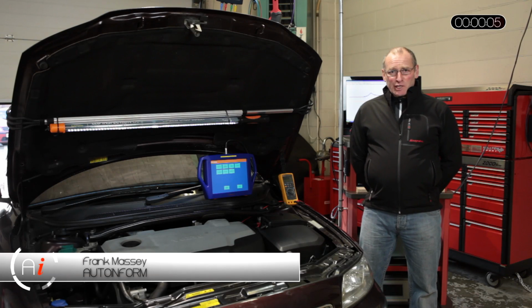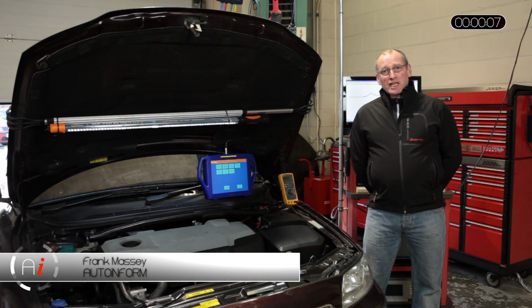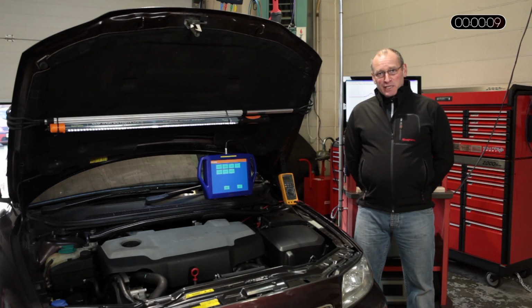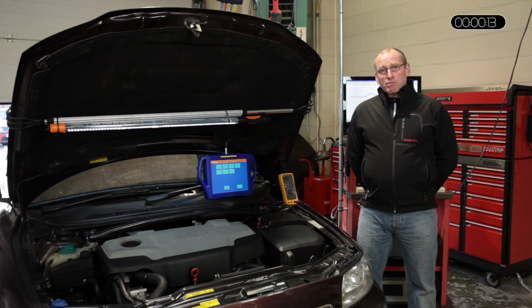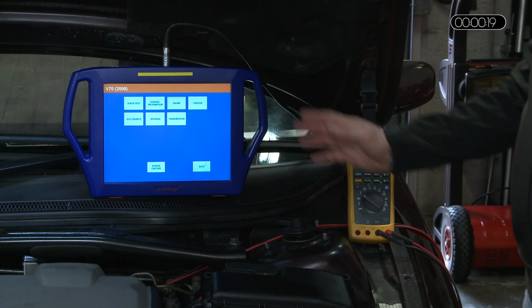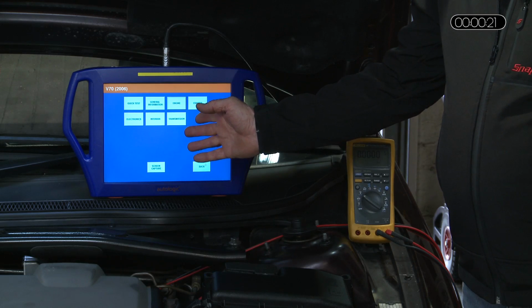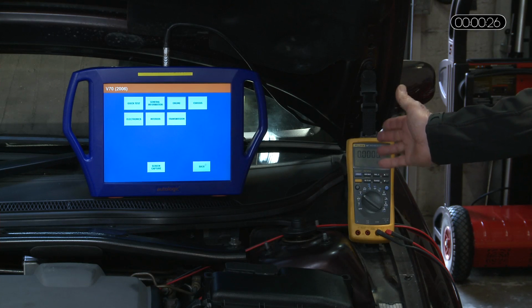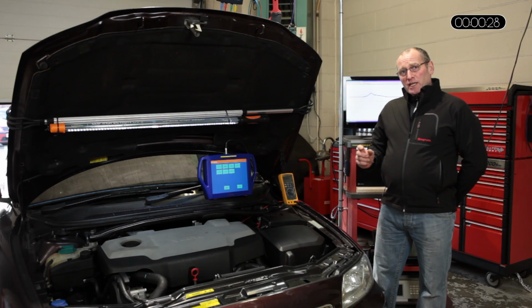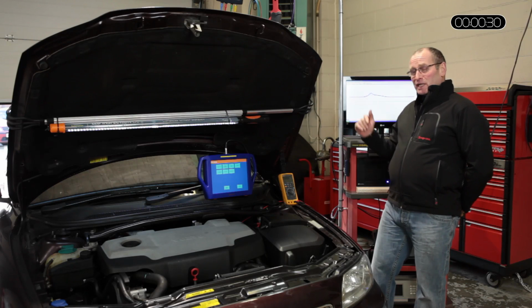In this diagnostic workshop feature, I'd like to take a look at diesel particulate filters. In particular, I'd like to go through the process through which we diagnose them using one of three methods: the serial communication platform, probably the most obvious method; simple voltage with a digital multimeter; and eventually imaging or profiling using an oscilloscope.